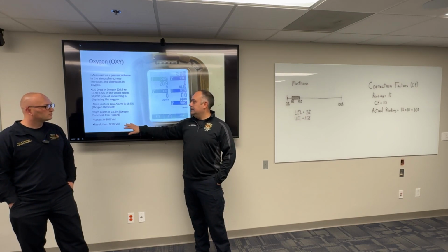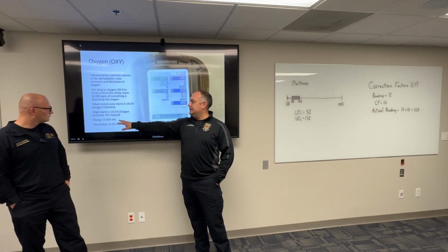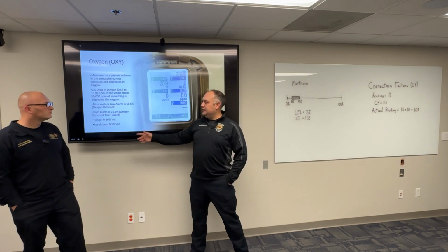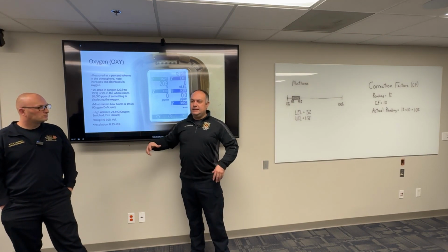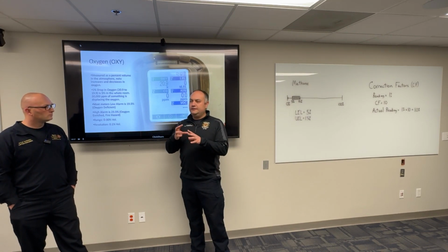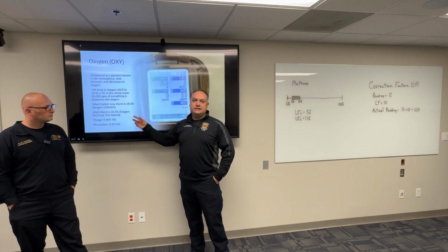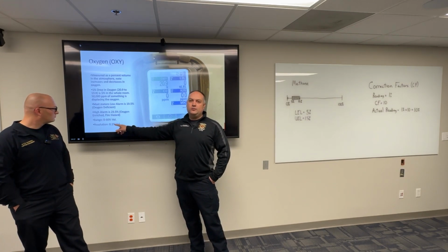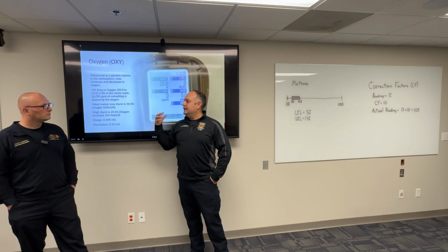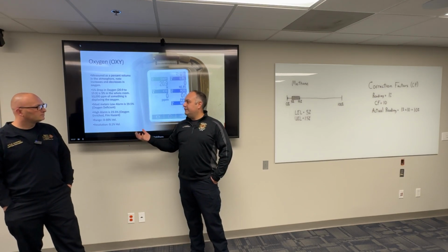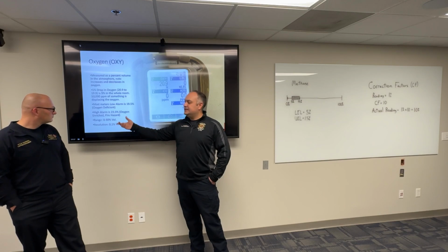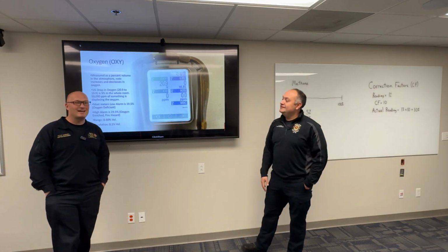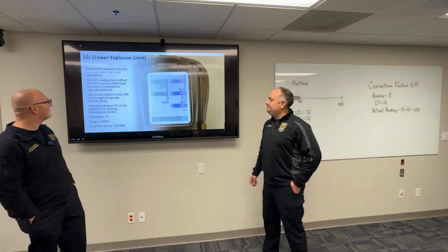Something to consider too, we listed the range and the resolution for each sensor. What the resolution means is that's the lowest measure of volume or percentage, in this case, that the sensor is going to read. So it's going to go up in increments of 0.1% instead of 1.0 or 0.5 or something like that. That's just something to be aware of, and you find that out by reading your manual like we all do. Yeah. Always read the manuals. That's how you find out all the information.